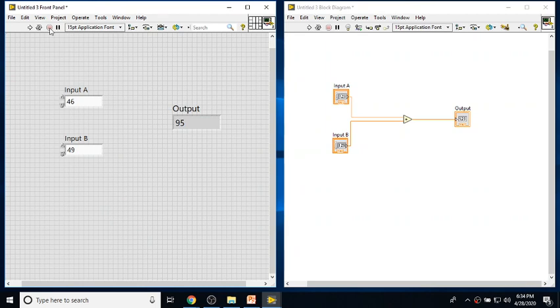So you're supposed to stop the code properly, making sure your hardware interface is properly terminated, not aborted. There's a huge difference between terminating and aborting. Aborting is an abrupt way of disconnecting anything, right? So I don't want anyone to start using abort. There are some times where your code doesn't respond, it gets into an infinite loop or a deadlock. There, yes, you have to use abort, but always try to have a habit of using run continuous or loops so that you can stop them, right?